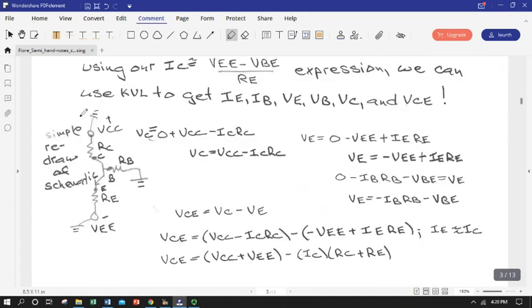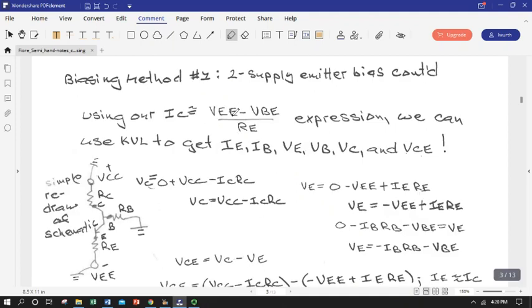So we've reproduced the circuit over here, very simplified, and sorry for the condensed picture, but we have ground, here's our collector supply, collector resistor, and then point C, which is our voltage at the collector input to the transistor. Point B is our base voltage, and these are all referenced to ground, B, C, and E, and our supply base. So here's a simplified schematic. And here was, from the other page, our simplified, if R sub B and R sub E are similar, our beta-independent collector expression.